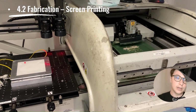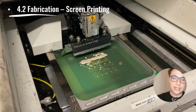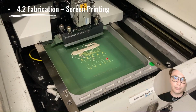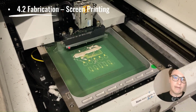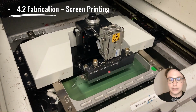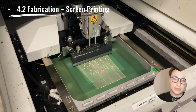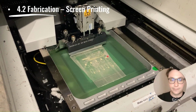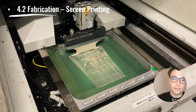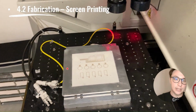So as you can see here, we have our substrate that goes below the mask. This is the mask we would like to use to print the electronics. We have a blade, a metal blade that spreads the ink around. It's a silver ink. And then we have the squeegee that applies a specific force and forces the ink to pass through the holes. And this is the final result, as you can see.